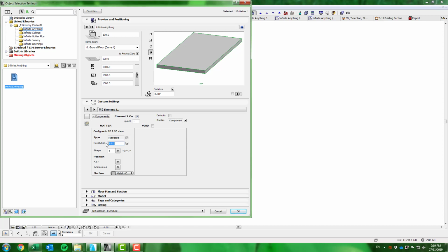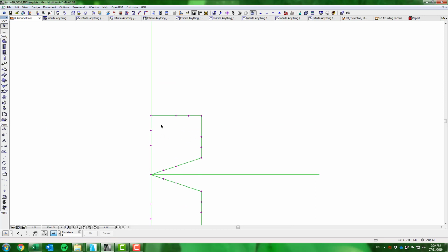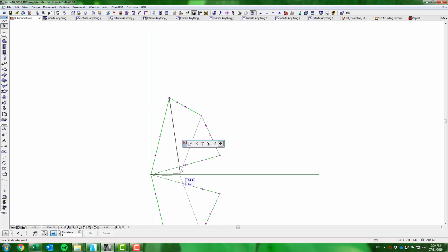Revolve should be 360 degrees. And then we just set the profile down here. So the revolve goes along the x-axis, so you have to rotate it 90 degrees, but I'll do that afterwards. So click OK. So here we got the guides for the revolve. Now I have to fix this up. This is actually the second node here, so this is a bit inverted. It should be in this position, and this node should be in that position. So just for now, when you go in, invert it like that. What you'll find is that this node can't actually go into the center position. It's not allowed.